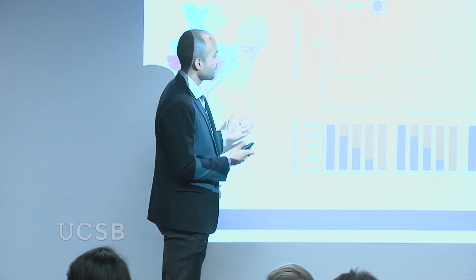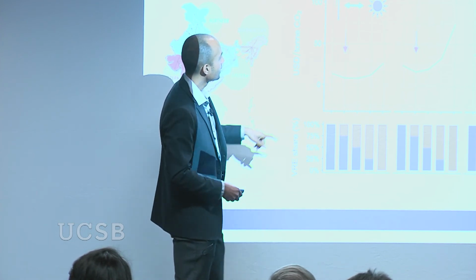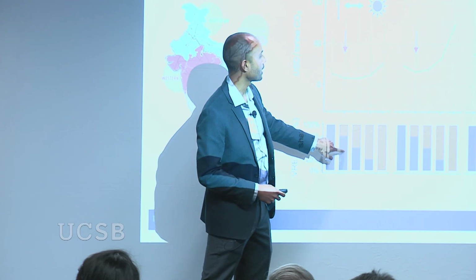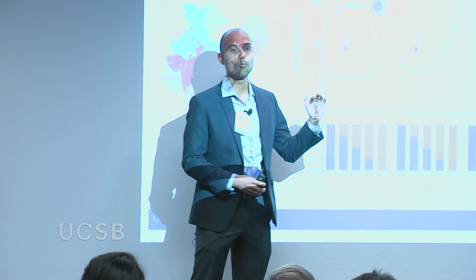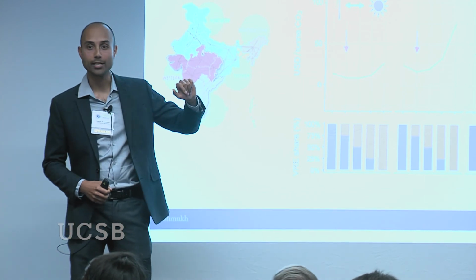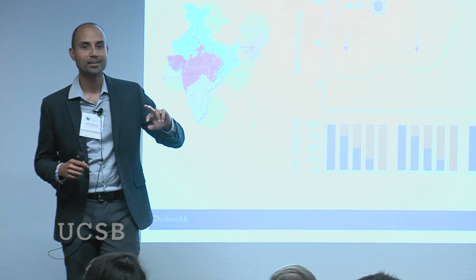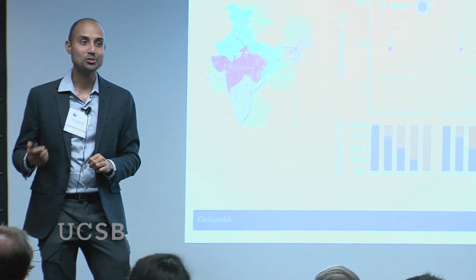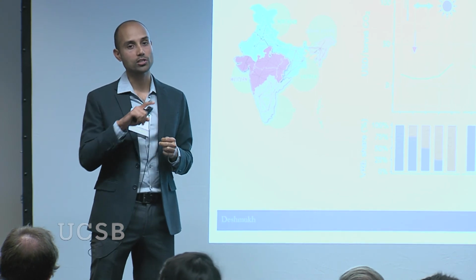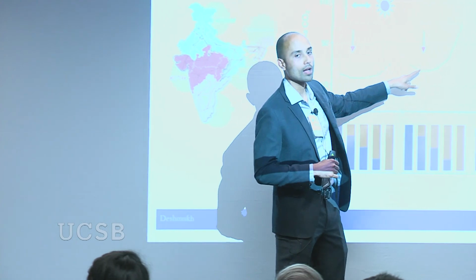So in all our scenarios, and this is just one, this base case, the 25% solar and 75% wind scenarios were always the least cost in terms of cost of emissions mitigation. Notice that this is exactly the opposite of the targets that they have chosen to pursue, even with aggressive assumptions for solar cost reductions. And the main reason for that is because you have to curtail solar.